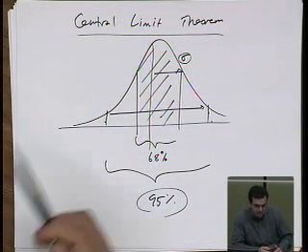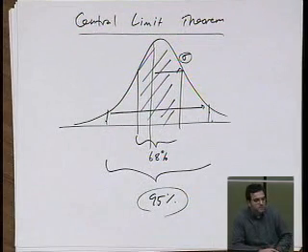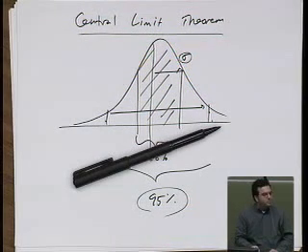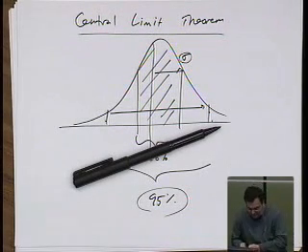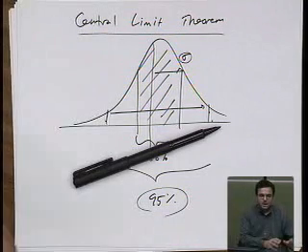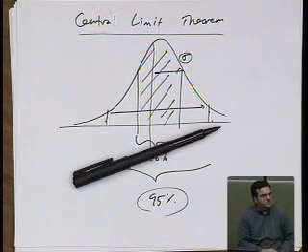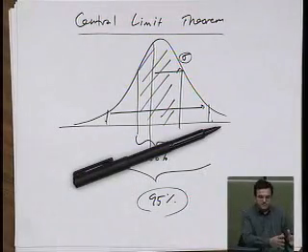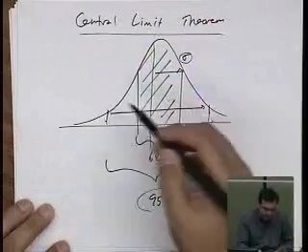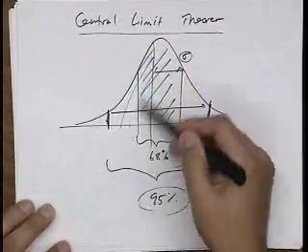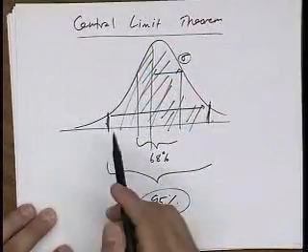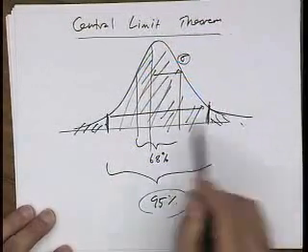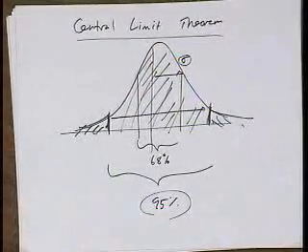That's right. So what the manufacturer does is they hire some cheap labor, and the cheap labor sits there and measures each resistor. If it's within 1%, they throw it in trash can 1. If it's not, they throw it in trash can 2. Trash can 1 becomes precision, expensive resistors. Trash can 2 becomes the cheap resistors that they sell. So basically, they're taking all the parts that fall in here and selling them to you, and all the parts that don't, they sell to you separately. So the distributions are these weird cutoff Gaussians, if you like. Okay?